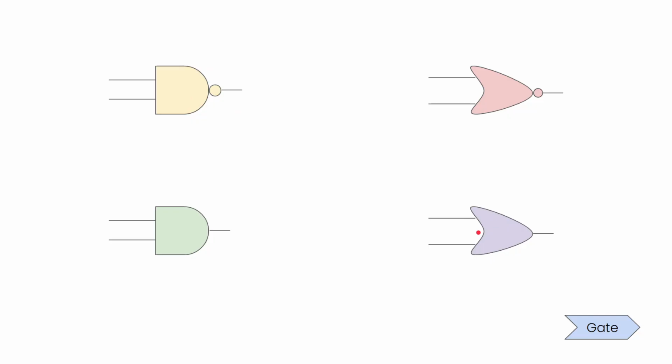And this gives us flexibility as designers so that we can choose which type of design we go with, which type of gate we use when we're creating circuits like, let's say, multiply accumulate units or multipliers, adders, things like that. Well, the quick version is we want to use NAND gates a lot, a lot, a lot.